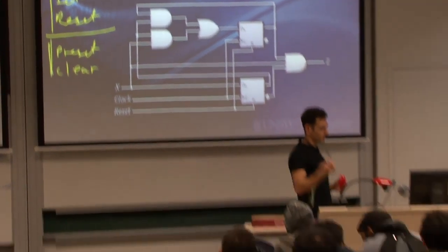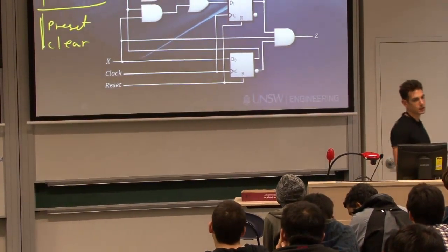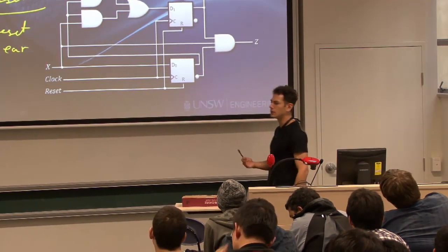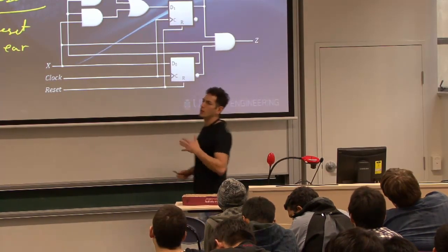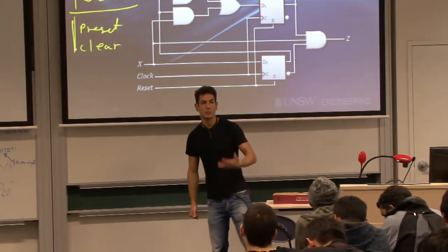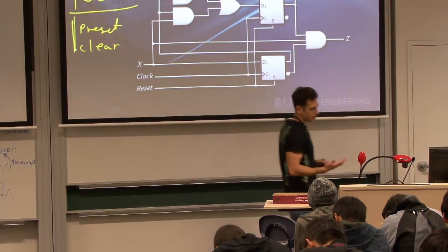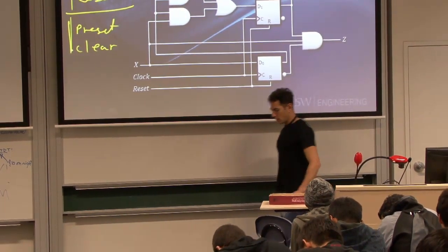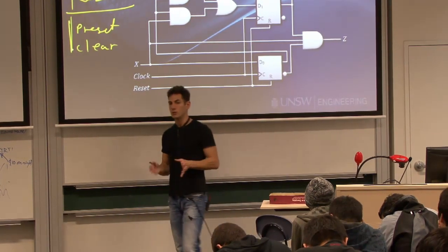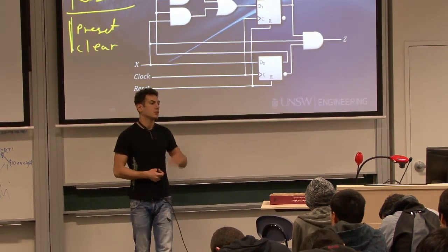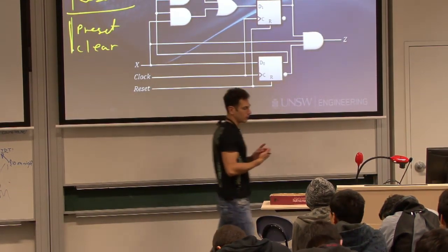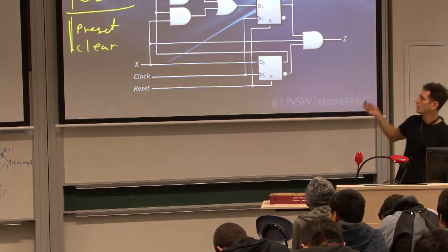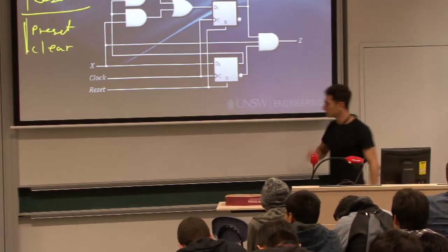From the state diagram, we went to a state table using the generic names for the states, the A, B, C, and D. From there, we've done state assignment or state coding, where we assign binary codes to each one of those states, filled the state table using those codes, derived the equations that will drive our flip-flops and our outputs, and then drew the circuit that will do this.